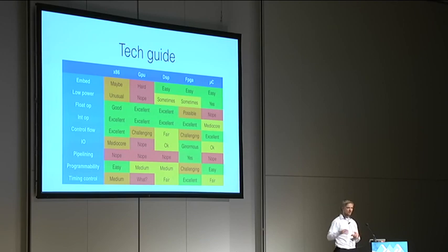The microcontroller obviously is at the very low end. Like I was thinking about an Atmel. It doesn't do very many floating point operations. And the FPGA, you can do everything, but the problem is that floating point operations are not well supported. In the latest vendor tools, they are claiming that they can do floating points, but they are very expensive in area and frequency perspective.